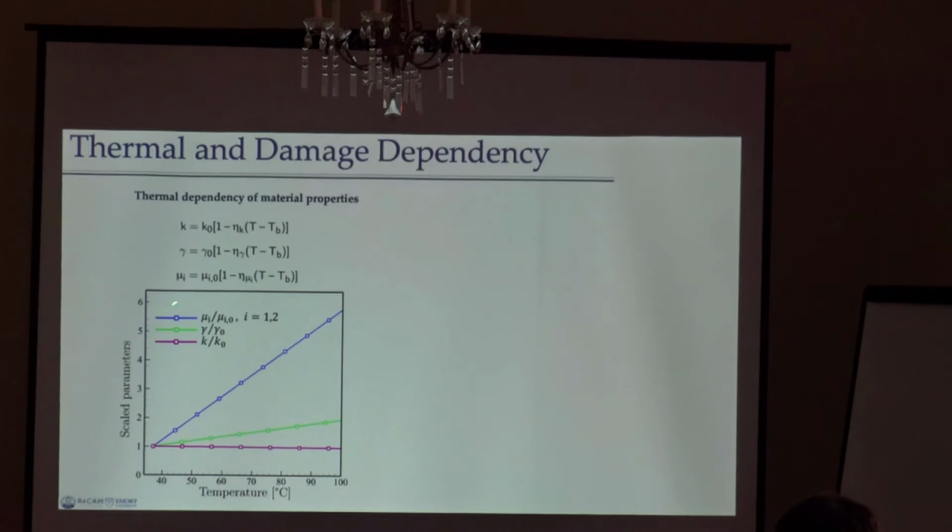And finally, in a first approximation, the stiffness parameters, the thermal conductivity and the electrical conductivity are going to change linearly with temperature. This is an assumption made in literature, even though we know that this is wrong for sure, because at some point, these functions have to saturate.